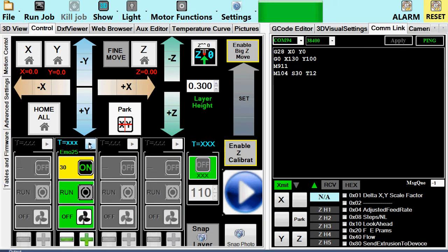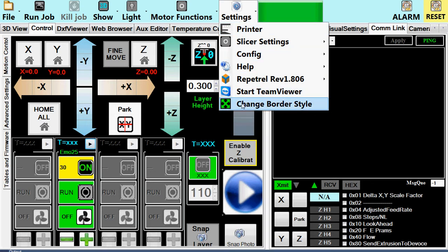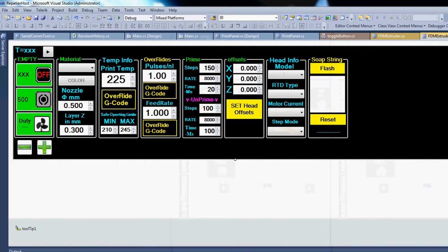And this is the way the printer holds its numbers. And so I'm actually going to unfold this. We're going to get rid of this, and I'm going to show you what that looks like. All those deck of cards together. They're right here. So you can see we've made the major interface, which is the control for the heater, manual on and off for the motor for just running out material manually so you can clean out your nozzle tip. Manual control of the duty cycle of the fan.